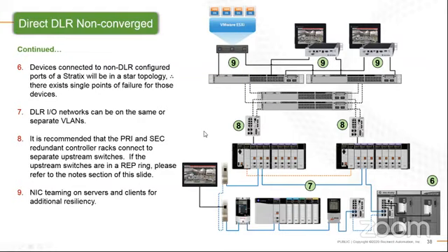As of V31, redundancy introduced an ability of having no swap over for ControlLogix when it comes to the IP addresses, which can heavily decrease the amount of what's called HMI blind time. So the amount of time that your FactoryTalk View system takes to be able to do the swap. For anybody that's not aware of what happens in redundancy, because we have a chassis A and chassis B, if you lose communication, you lose power to your chassis A, which is your primary, the secondary will take over.